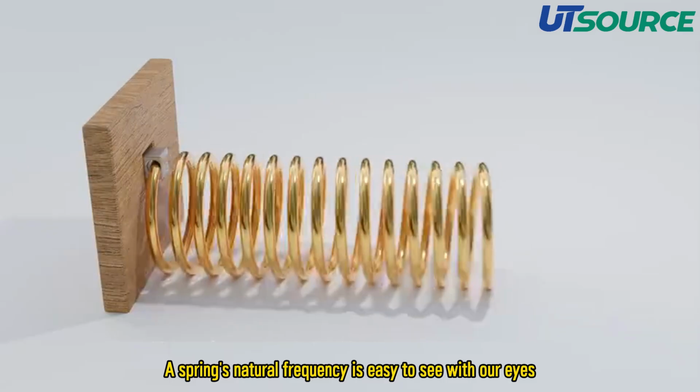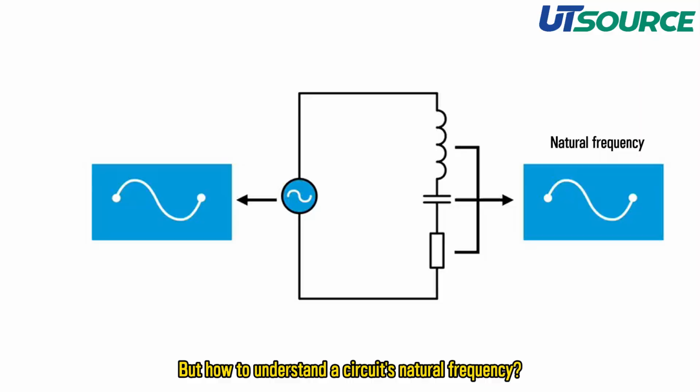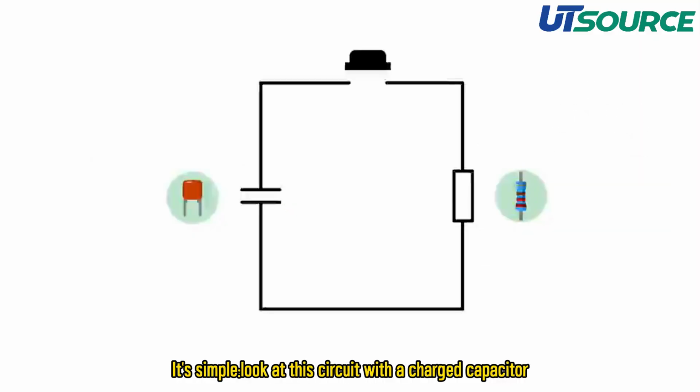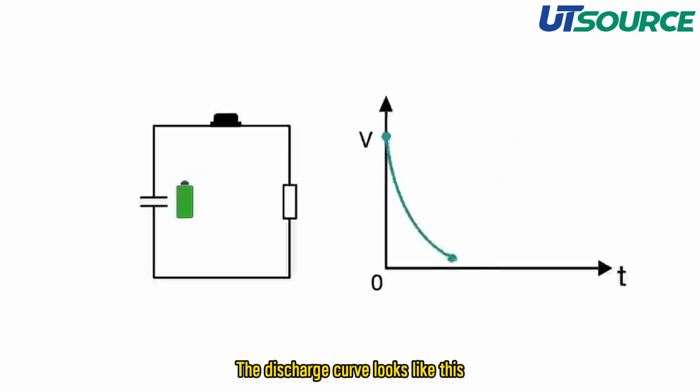A spring's natural frequency is easy to see with our eyes. But how to understand a circuit's natural frequency? It's simple. Look at this circuit with a charged capacitor. If the switch closes, the capacitor discharges quickly, energy mostly lost in the resistor. The discharge curve looks like this.